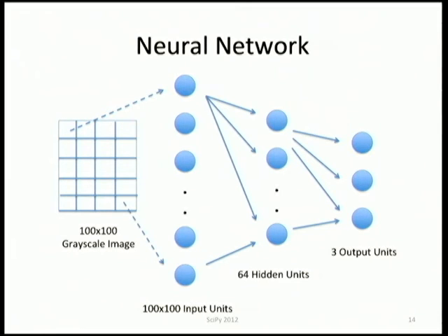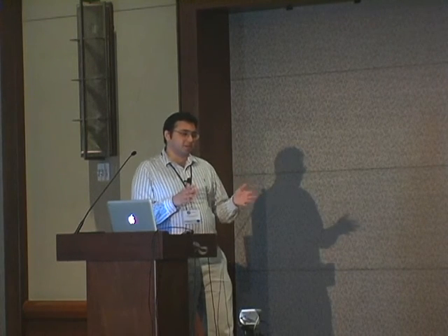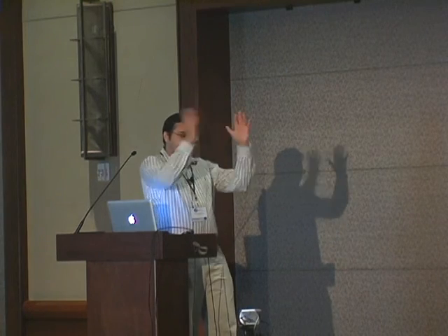Now, going back to your point, some of the failure modes of this thing: the robot only had these 3 constrained actions, it can move forward, it can move left, or it can move right. And again, the motors are running for a specific duration, and accuracy is a problem. So sometimes the robot would overshoot, go a little bit too forward, and almost land on a white piece of paper, and then all it can see is just white paper close by. And that's really no good. Like, what can you do in that situation?